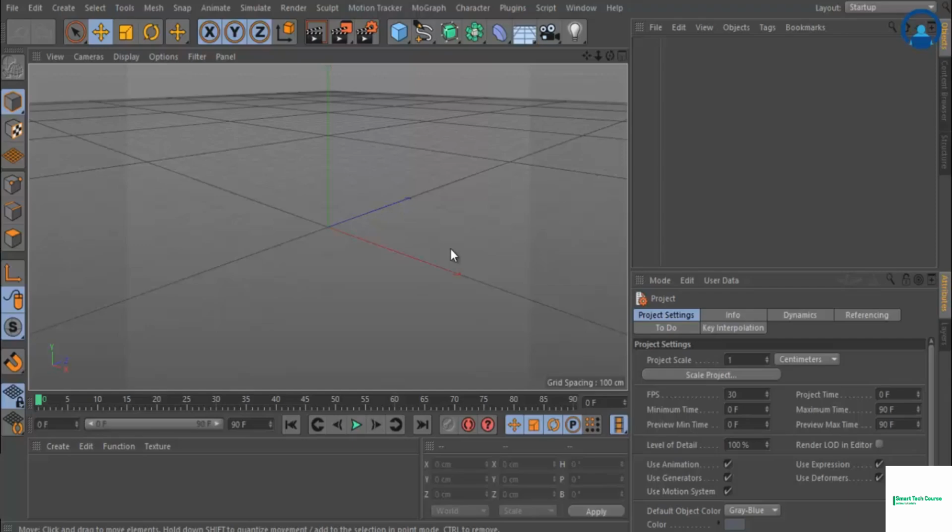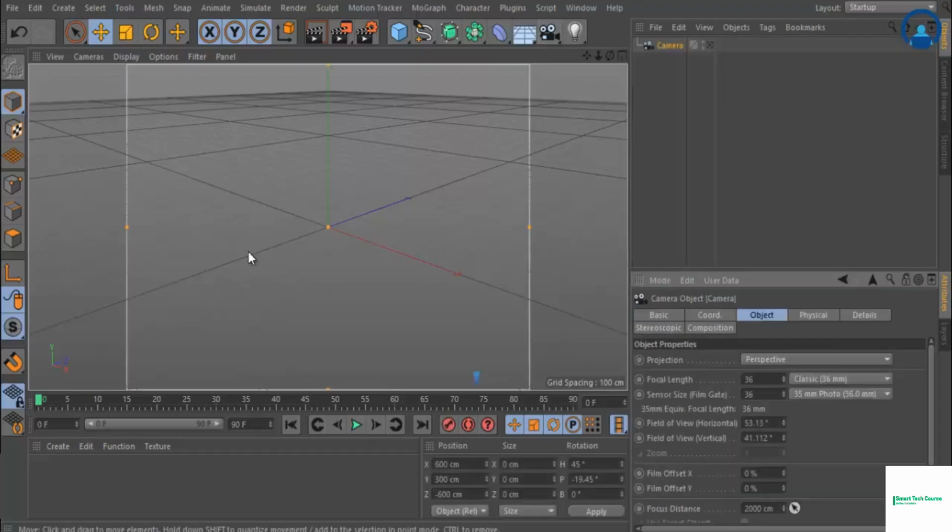We normally use different kinds of software especially for this purpose, 3D tracking software or 3D match moving software like PFTrack, Boujou. But we can create the same effect inside Cinema 4D by using some basic tools. So I show you a very small example of this technique. For that, first I have to create a camera. So I click over this option and I create a camera over here. Right now we're seeing through that camera.